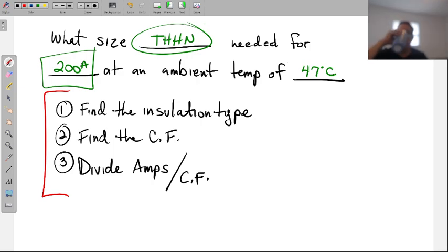Is it a 4-aught wire? I don't know, but it sounds like it probably will be. I found 3. We got a 3-aught. All right, we're battling it out. One person 3-aught. Now here's the thing. The 3-aught person, if they send me that bid, I'm going to think that's a cheaper bid. So will I go with the 3-aught person? But here's where it matters: if they're wrong in their calculation, they eat that cost. If the inspector comes and says, hey, this is supposed to be 4-aught, they eat that cost. I pay less and they pay more. So here's where we want to make sure our wires are sized correctly.